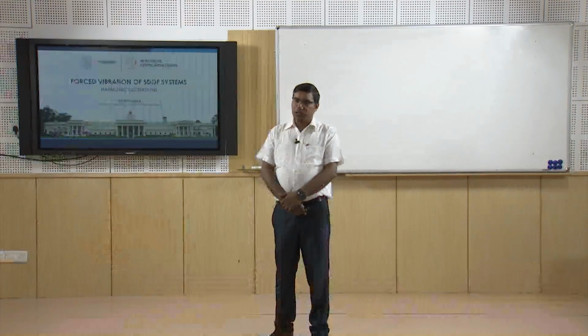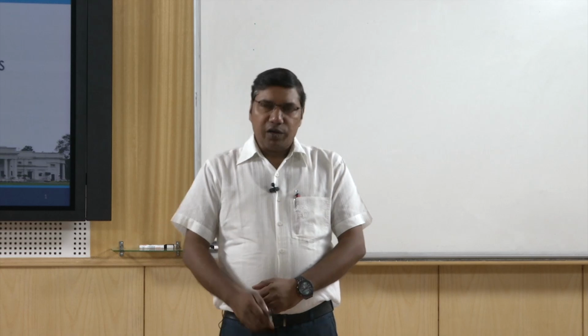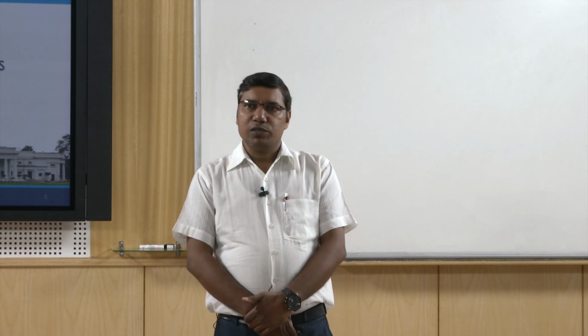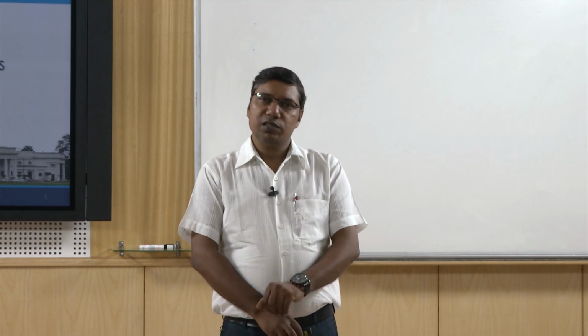Welcome to a lecture on the forced vibration of a single degree of freedom system. So far, we have discussed the free vibrations of a single degree of freedom system. We discussed the free vibration under viscous damping and Coulomb damping. So, in free vibrations, we did not apply a force continuously on the system, but we just gave some initial disturbance to the system and left the system to vibrate, and the system vibrated with its own natural frequency.